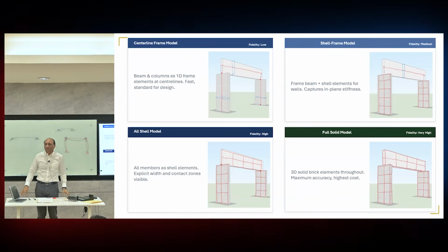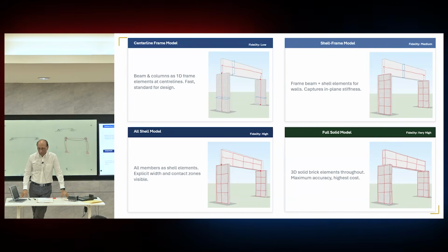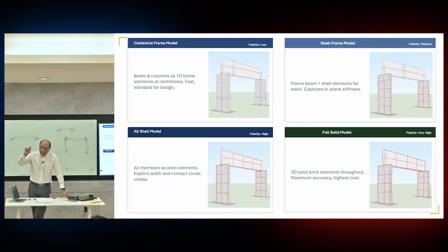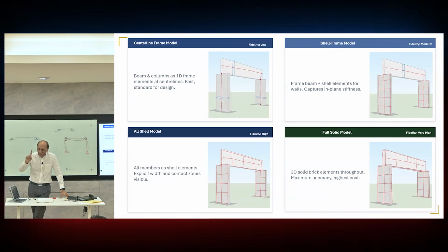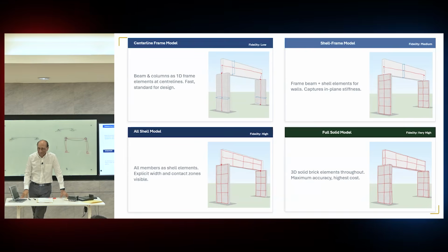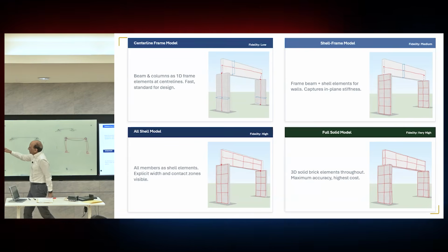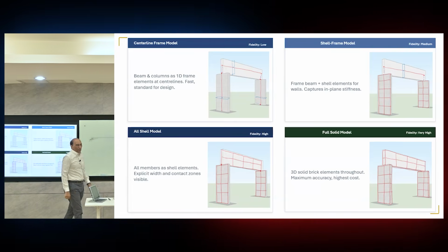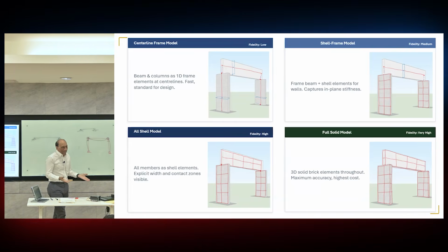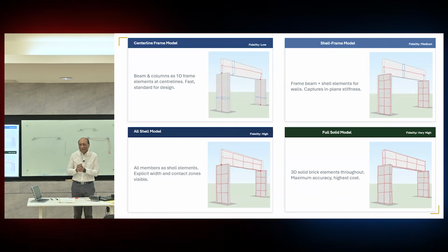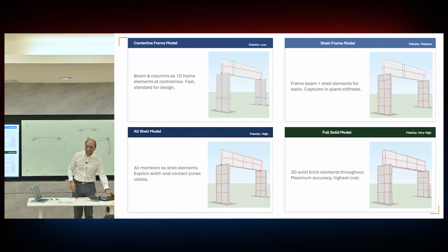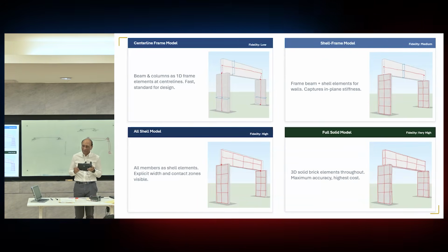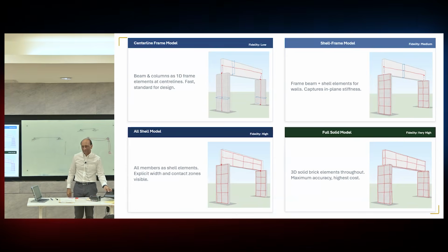So create your virtual rigid zone. You put another small element on top of the column, not shell, frame. We're talking about frame. First is frame element. You cannot use any other element. First is a frame, centerline frame model. You cannot deviate from centerline frame model theory because that's all I have in my software. I'm trying to bring you back to this level, that in this program, all I had is a 2D frame analysis program. What will you do with that?